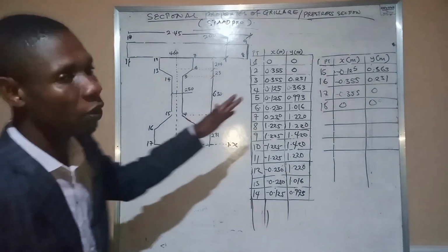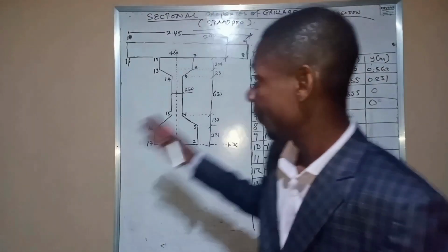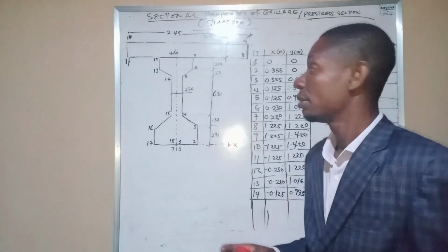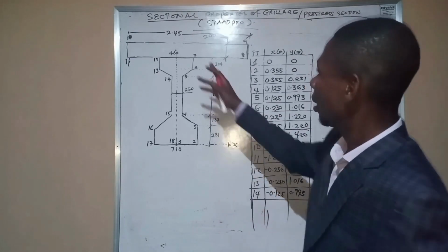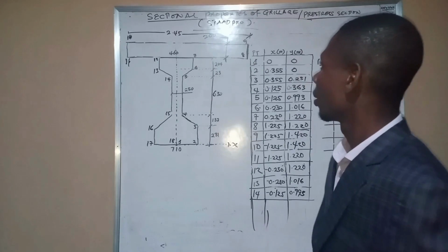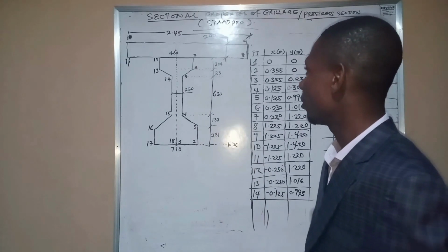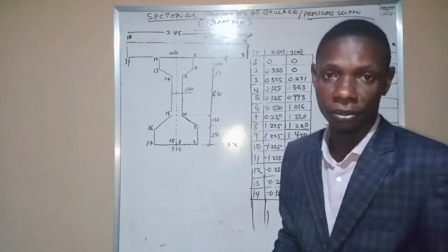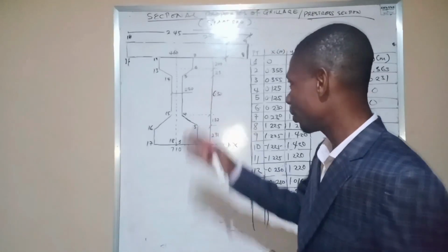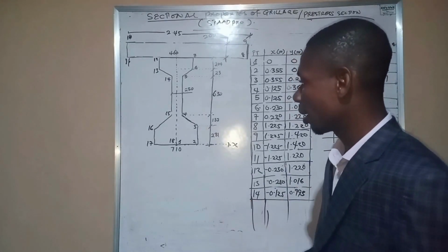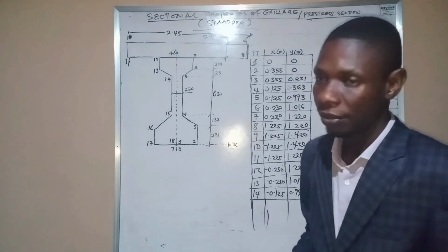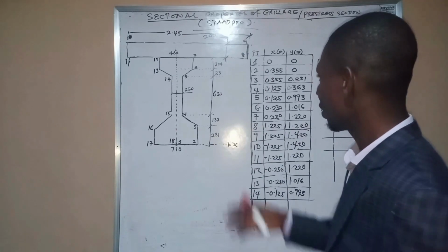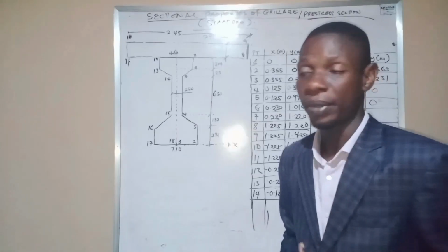All right, so what we've just gotten now is for the Grillage analysis. Now if we want to work on prestress concrete design, our modular ratio will be used to multiply 2.45 before we apply it, if we intend to use that to obtain the section, or we intend to use the parallel axis theorem to obtain the section of the prestress beam. So whichever we intend to use. Remember that this is a composite section of prestress if you intend to design it as prestress concrete.